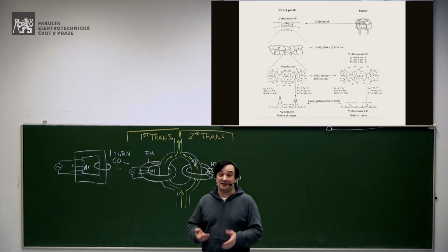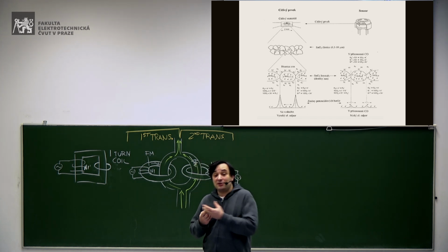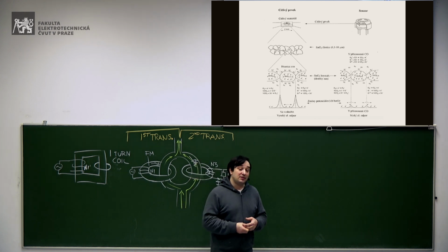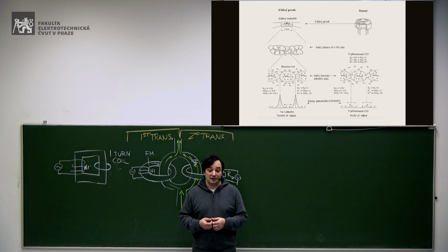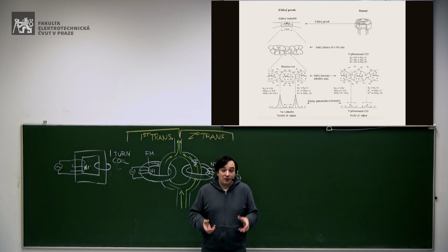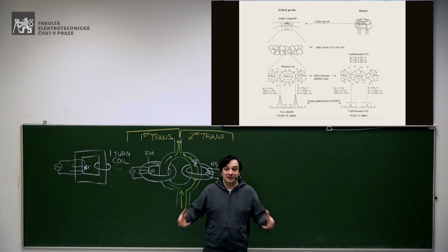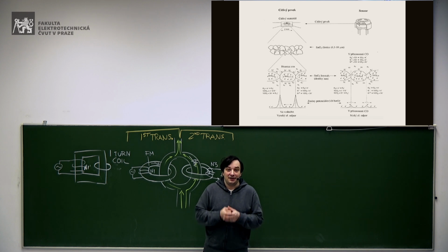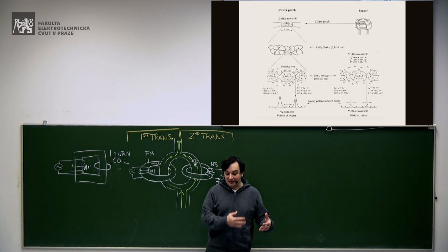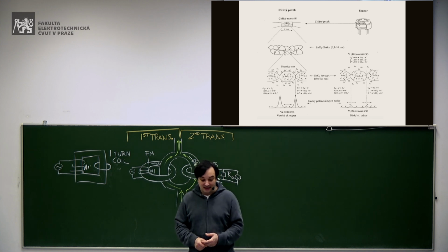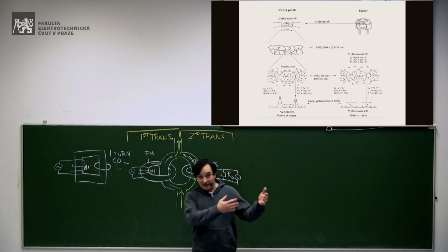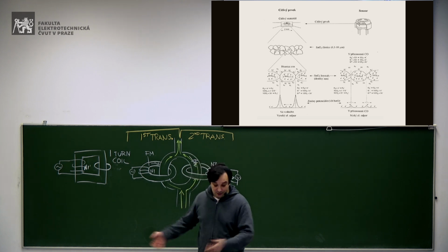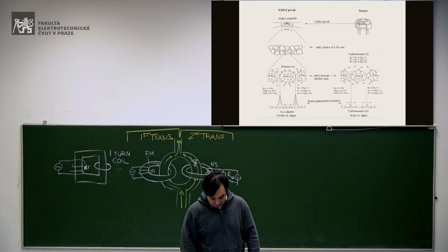But as a matter of fact, these sensors are used not to measure the presence of oxygen itself, but to measure the presence of other gases which react with oxygen. If the other gas gets there and takes the oxygen away, it doesn't affect the tin oxide anymore, the potential barriers decrease, the current can flow, and so the resistance decreases.